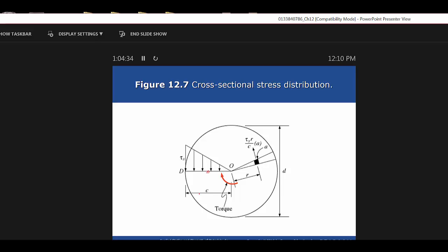Because it's like, well, wait a minute, why wouldn't I use the inside diameter, and divide that by 2? Well, you're trying to find the max, and the max is out at the outside diameter, isn't it? Make sense? So that's why you use the 75 there.